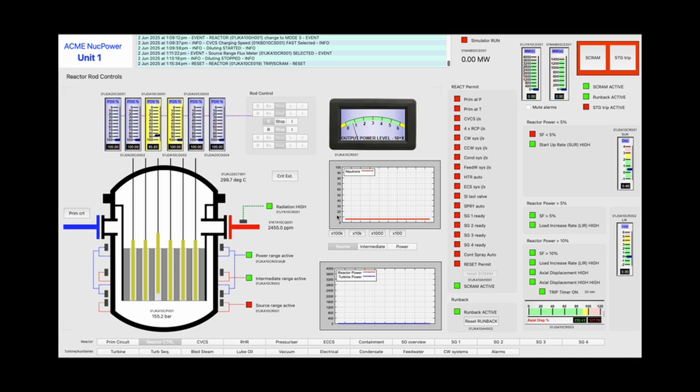To ensure we do not introduce too much reactivity to the system too quickly, we must follow the startup rate gauge on the right of the page. A startup rate of 2 is the limit for safe operation. If the rate reaches 3, then the reactor will automatically trip and you can start again. This startup rate measures the increase in reactivity from one moment to the next.